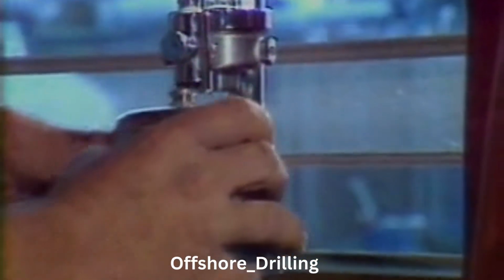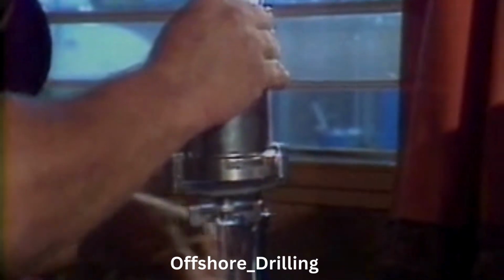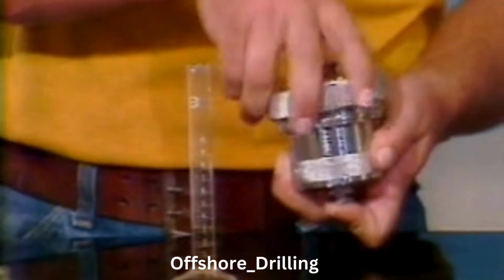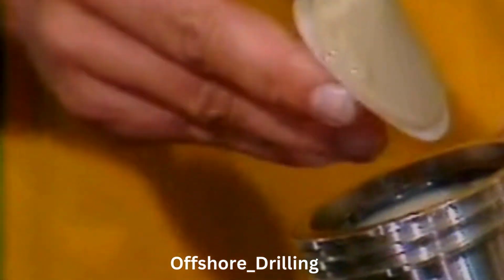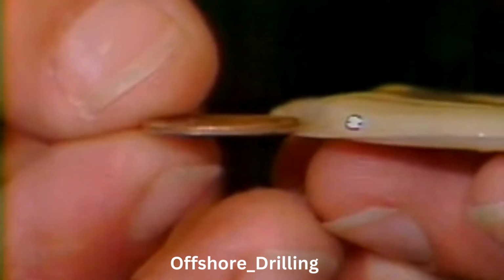Before too long, the mud particles are going to try to clog the filter paper and slow the flow of liquid that's squeezing through. The amount of filtrate, or filtered liquid, is measured and recorded. Then the lid is unscrewed and the filter paper is removed. This is the filter cake here. It's the thickness of the mud layer that got deposited on the paper after 30 minutes.